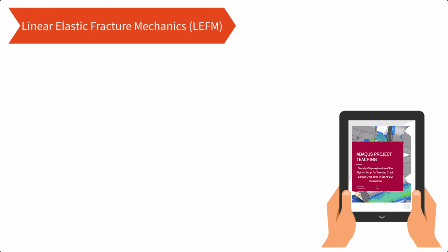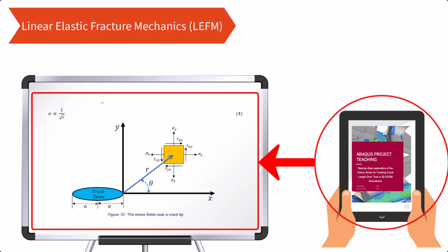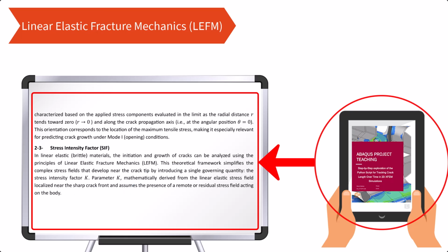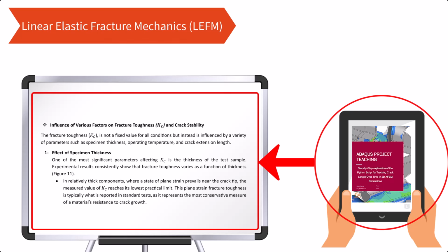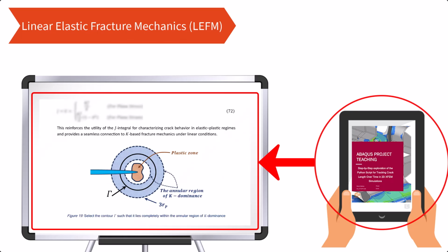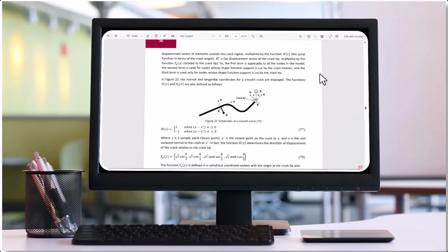We have also thoroughly explained topics such as linear elastic fracture mechanics, LEFM, along with its associated concepts, including energy equations, stress singularity at the crack tip, the stress intensity factor, SIF, and fracture toughness, detailing how they all relate to one another. Furthermore, key relationships are examined in detail, such as the connection between the J-integral and fracture toughness, and the interplay between fracture toughness, the strain energy release rate, G, and the stress intensity factor.